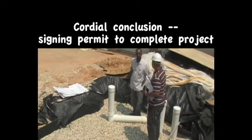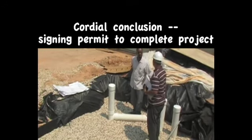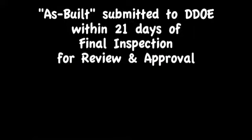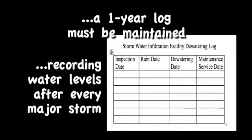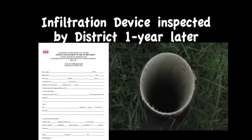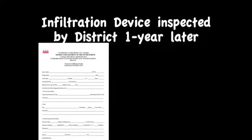No permitted stormwater BMP is complete until a final inspection has been conducted, and what is known as an as-built of the completed facility has been submitted to DDOE within 21 days of the final inspection for review and approval. After the as-built plan has been approved, the building permit applicant receives a final approval notice for the completed stormwater BMP, and a maintenance and operation inspection will be completed within 1 year.